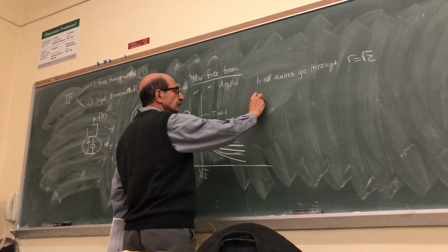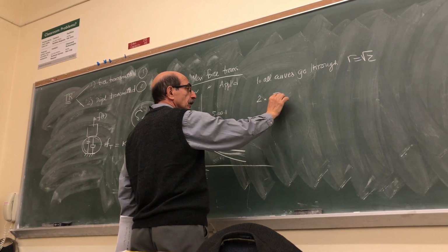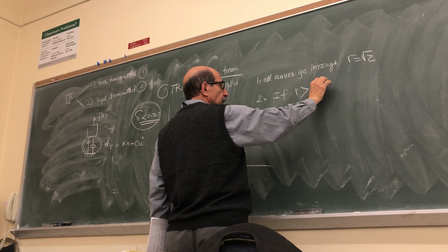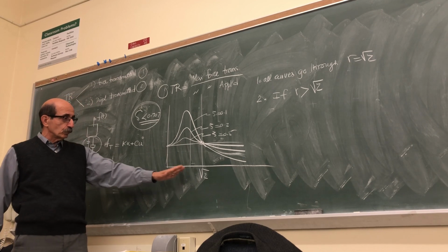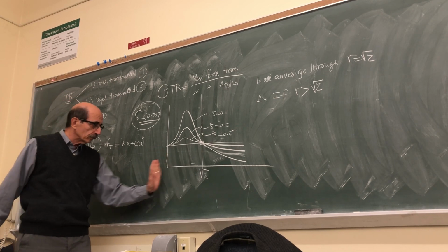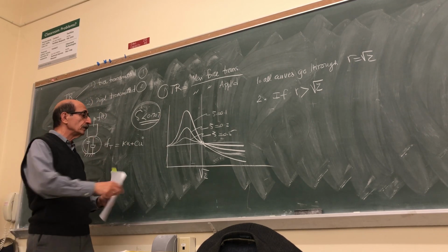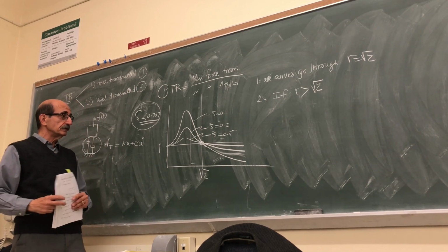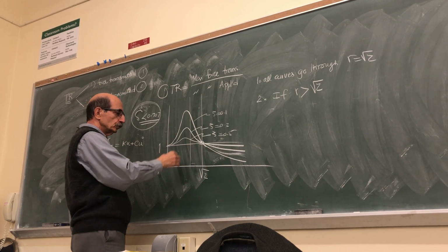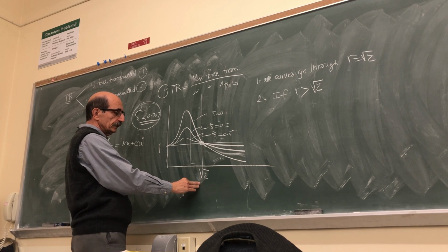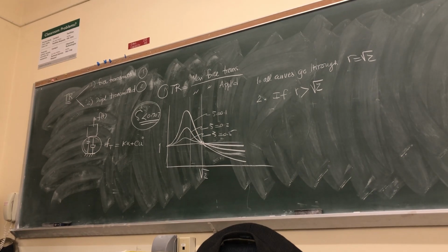The second observation we made was if R is greater than the square root of 2, which is what we ideally want, because less than square root of 2, no matter what range of frequency ratio you are, the transmissibility ratio is always higher than 1, which is not really desirable, right? So first of all, you really want to make sure that R is greater than square root of 2 by choosing the right stiffness, right support system.